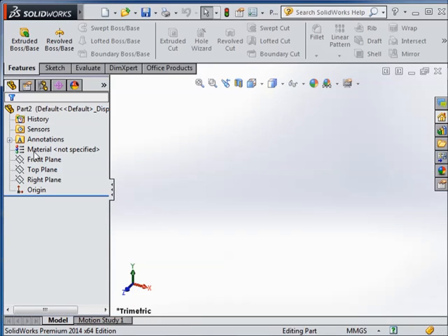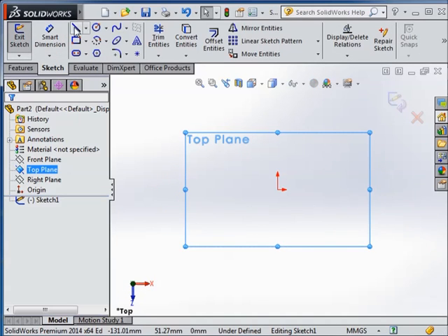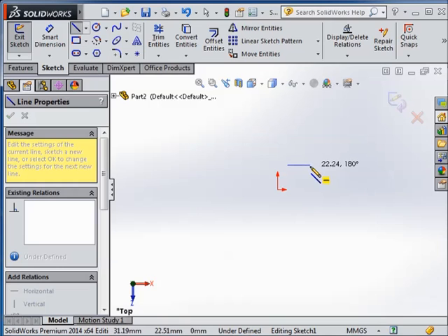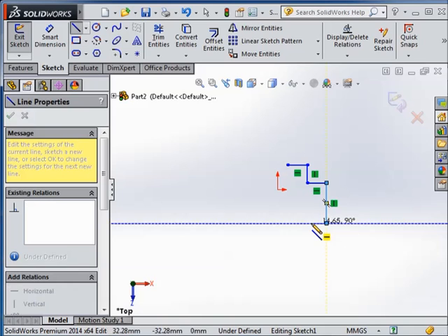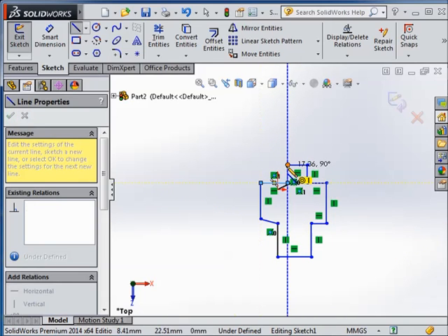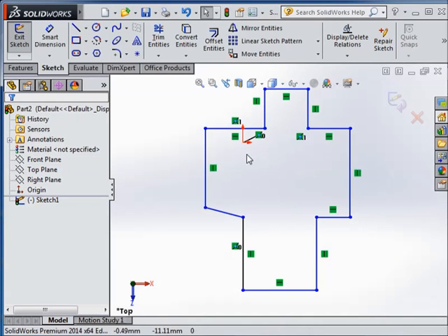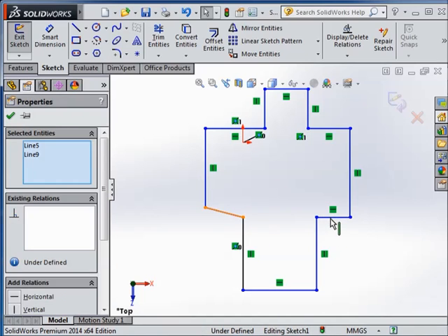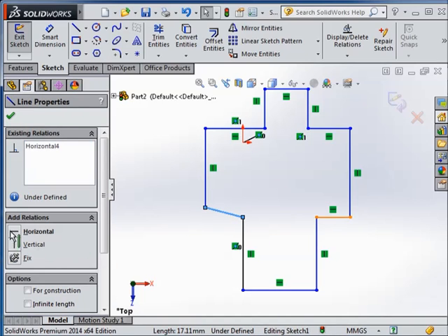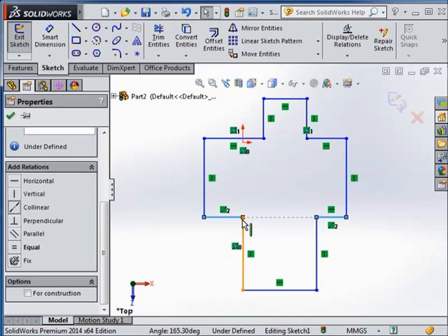This is where you're going to hold all of the dimensions and the drawings which will define the multi-layer robotic device. Now, since we're doing laminate robot design, you want to define everything in a sketch, and then all of this geometry will be determined in a single place. So what we're doing right now is creating the outline of the robot, which can then be dimensioned, and the same sketch can hold the inner scores and folds of the robot design and cuts, but they need to be made out of construction lines.